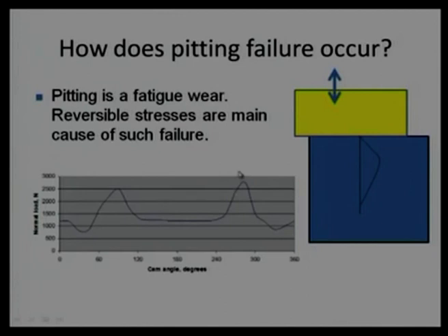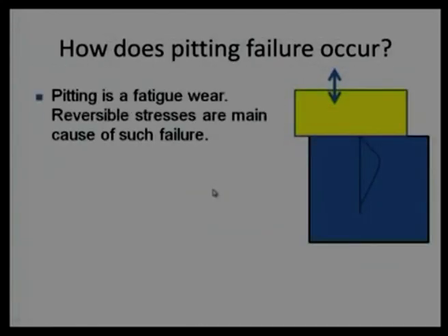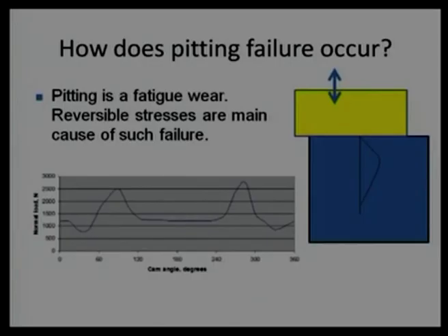And here what we are referring to is the top axis. If I go back, this is what I am saying, this is the axis, I am assuming 0 degree of rotation, and this is exactly 270 degree. So, whatever we are thinking, that pitting wear has occurred at 270 degree, the same thing is shown over here. The maximum force is around 270 degree, but I cannot conclude just by finding the force how much force is generated at the interface. We need to do more analysis.